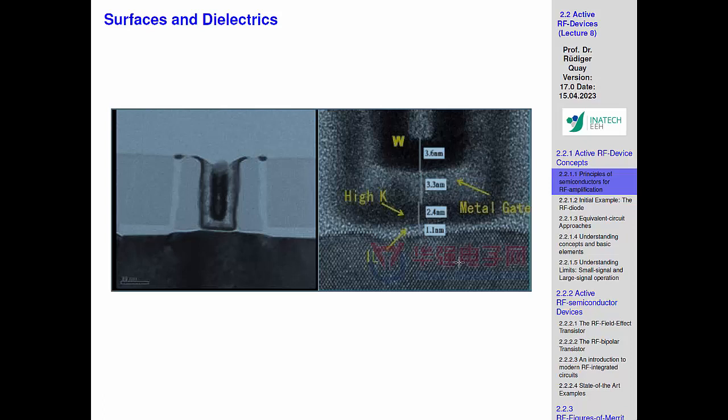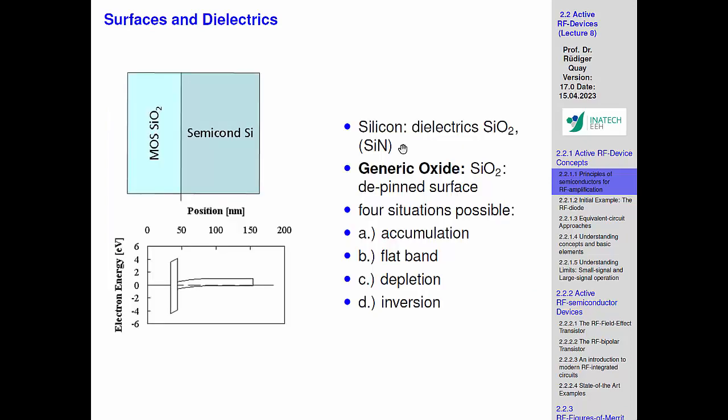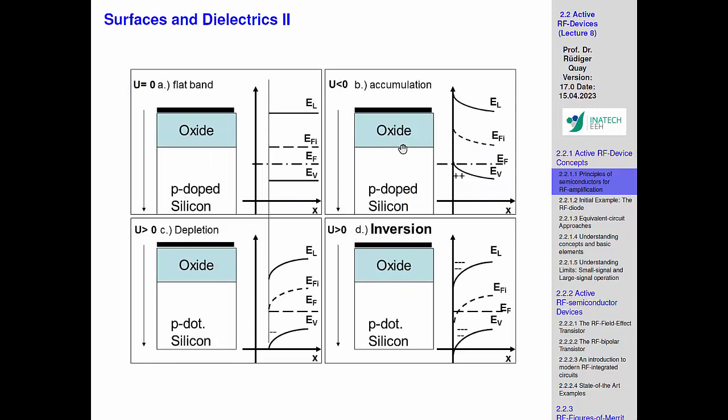They have the same properties like the silicon dioxide, but they form a stronger barrier, because if you just had the silicon itself as a barrier, the problem is things simply get too leaky. That's why people were a bit worried, and they started to exchange that, because the barrier you build towards the metal on top is just enhanced by the additional barrier that you create by a high K dielectric. Yeah, so that's an idea. So you want to essentially maintain the situation, although it's not just a normal oxide, it may be hafnium oxide or something else. It's just an improvement of this situation.